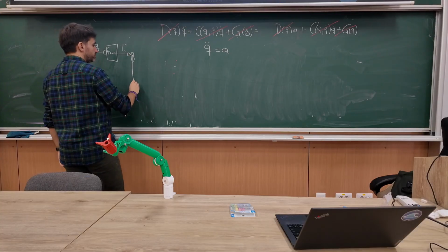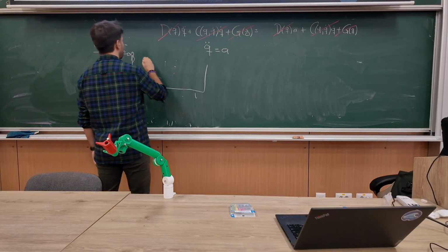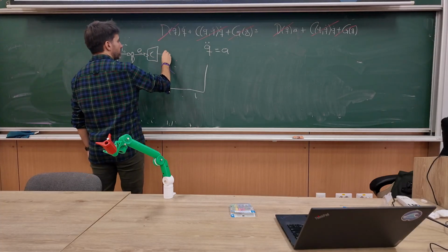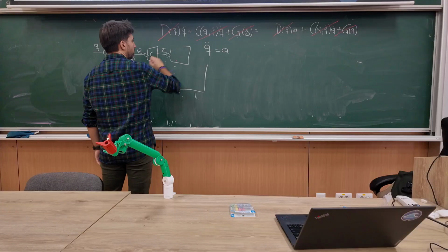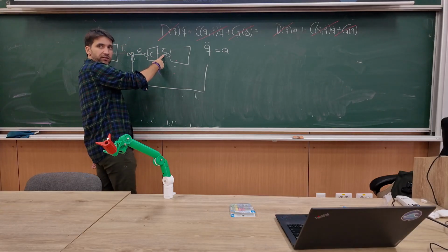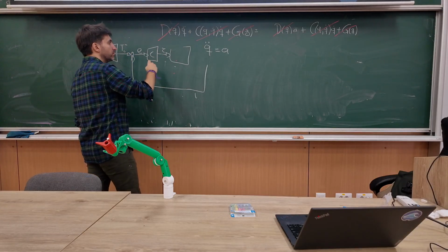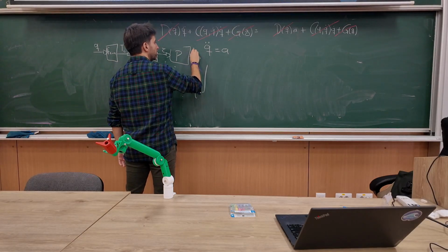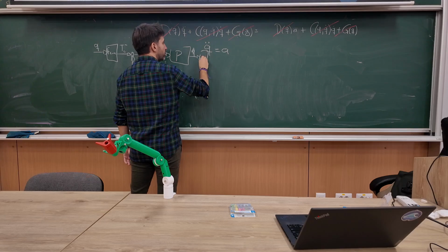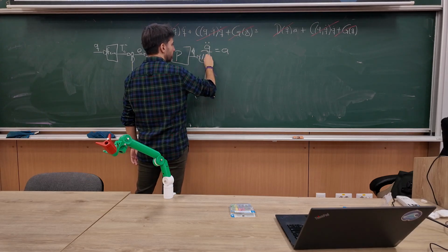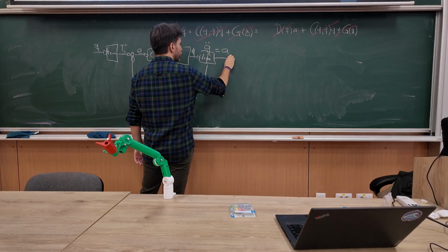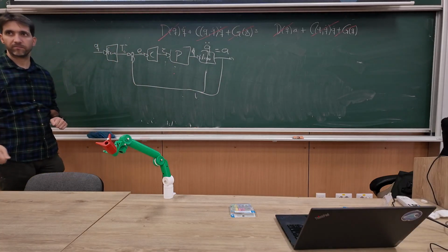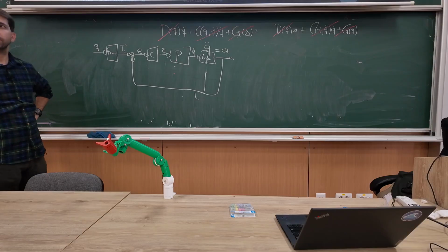Calculate the error, and then feed that to the controller, and the input is what? It's still torques, right? Because that's what I'm talking to, right? And then you say, okay, I measure joint coordinates, and then do again forward kinematics here, right? F kine, and then take this thing basically and calculate the error. Yes, but I do the same thing twice.